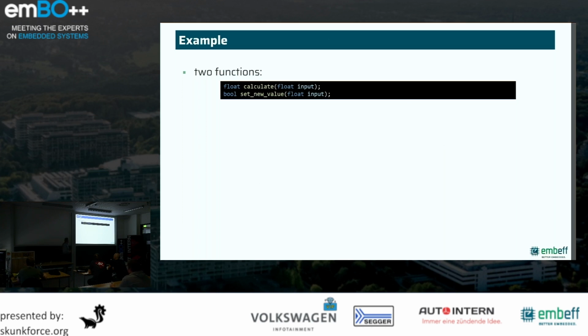So, the other thing, for our software, we find out that those are our constraints that we have to fulfill. The time that calculate takes plus 2 times set new value should be less than 40 microseconds. This 40 microseconds is coming from some kind of requirements that someone wrote, and they measure that, for example, our brake system in the car, from the input to output, it must be maximal this value. We have also the other constraint. It's this one, that the calculate itself should be faster than this value.